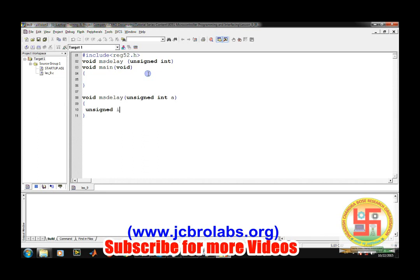So unsigned int i, j, and then for i equals 0. Okay, let's make it t. i equals 0 till i is less than t, i plus plus, and keep on making this program run. j equals 0 till j is less than 1275, and then j plus plus, and it will keep on moving here. So this is the delay subroutine.